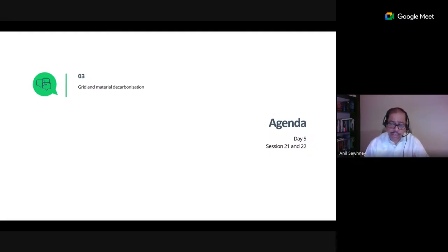I gave the example of biogenic carbon. By using timber, you are benefiting the environment because you're storing carbon in the timber beam in your project. Static LCA does not give any benefit of when the emission took place. Did it take place 50 years from today, or today? They are all treated the same, whereas dynamic LCA treats it differently. It gives you credit for storing carbon.